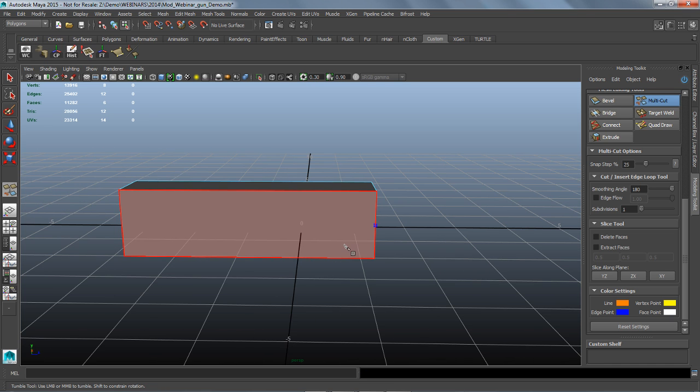So that's kind of nice, so that I don't have to commit, undo, and then redo my entire cut. I can get into here and actually simply undo as I go. One of the things you'll notice here within the extension release, I'm holding down Control and Shift, and I'm getting this nice little perpendicular green highlight. What that's giving me is 90-degree cuts. So I can now go in and get exactly 90-degree cuts to the cut that I'm working with.